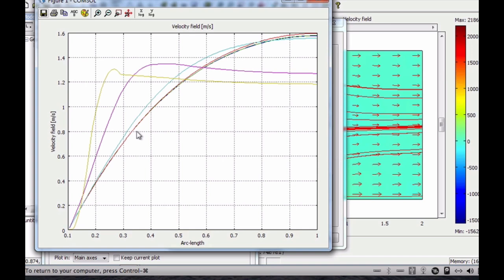This one here, I'm guessing, is the very small Reynolds number, so 10 to the minus 2. We did it for viscosities of 100, 10, 1, 0.1, 0.01, 10 to the minus 2, and 10 to the minus 3. So 6 of them, there should be 6 curves. And so individually, those curves should be for Reynolds numbers of 10 to the minus 2, 10 to the minus 1, 1, 10, 100, and 1,000, right? And so these would be the low Reynolds number curves.